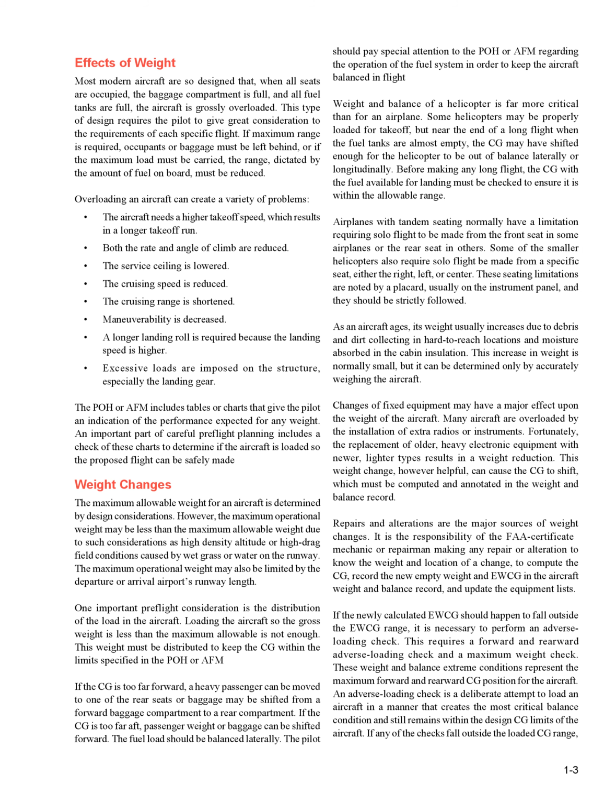Weight changes. The maximum allowable weight for an aircraft is determined by design considerations. However, the maximum operational weight may be less than the maximum allowable weight due to such considerations as high density altitude or high drag field conditions caused by wet grass or water on the runway. The maximum operational weight may also be limited by the departure or arrival airport's runway length.